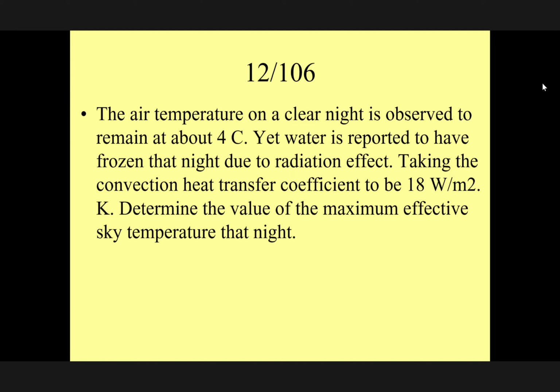We have radiation and convection. Convection or conduction? Convection. Therefore, you write a simple energy balance for the surface. You mentioned this reaches equilibrium at this moment. The temperature of the surface of the water is 0 degrees, and therefore there is convection between air and the surface of the water. And then also this surface of the water is radiating to the sky, losing energy to the sky,